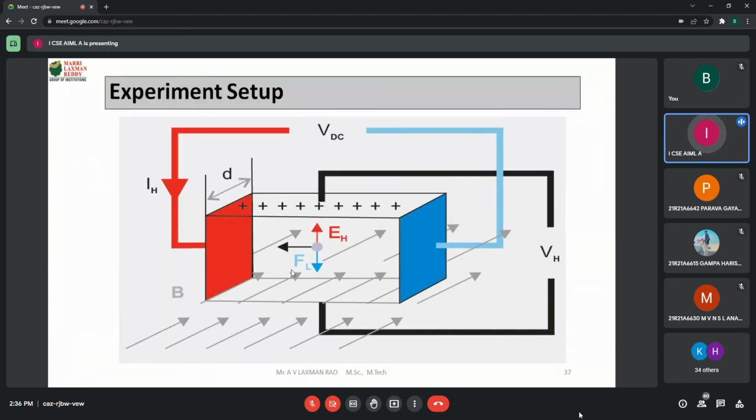And that diagram you need to draw. This diagram you have to draw by taking three axes, X, Y, Z. This is the semiconducting material, a three-dimensional semiconducting material. Now, in this direction I am applying the magnetic field B. Arrow marks you see, and I am applying the current in this direction, perpendicular to the direction of B. Then voltage is developed in the top and bottom direction. So VH in the top and bottom direction like this.